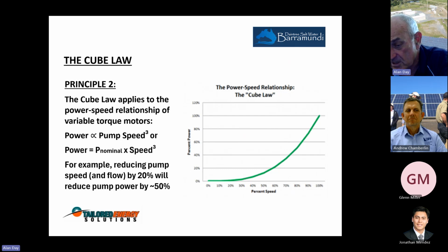Basically what you're going to do is set it at 90% and see whether that maintains the oxygen levels you need in the water, because they measure oxygen levels all the time, regularly. Or can you run it at 80% and will that give you the volume you need? There are more sophisticated ways to do that. We've worked with a company called OxyGuard, where they use automatic oxygen probes to vary the speed of the motors. But that's getting into some fairly big numbers for cost. This is a way to achieve something that could be very good, much more cost effectively.